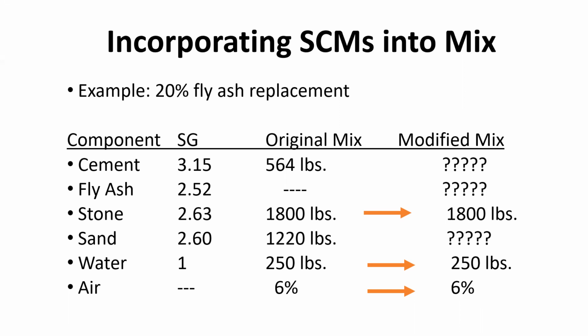We'll figure out how much volume the cement and the fly ash take up. We already know our volumes for our stone and water and air, so we'll just take that out. So 27 minus everything but the sand, and whatever that number is, that's the sand volume. We use the sand to balance it out to equal 27 so it yields properly.